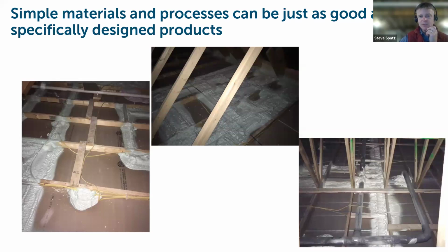These are just some examples of what you'd see typically in an open attic assembly, where the ceiling drywall is essentially your air barrier. It's providing a lot of different roles actually in an open attic: flat air barrier, vapor control, and holding back the thermal insulation as well. But just going through and spray foaming closed cell foam over all of the penetrations and top plates of the wall, stitching together what otherwise would be a bunch of broken up sections of drywall around an overall attic plane, with a lot of pathways for air leakage.